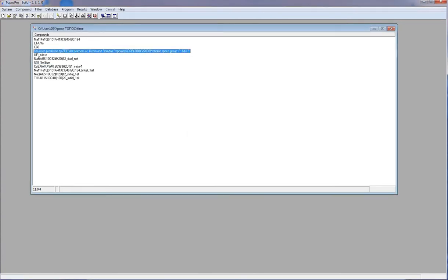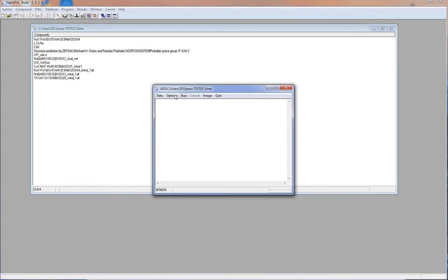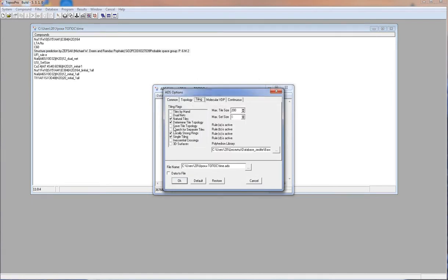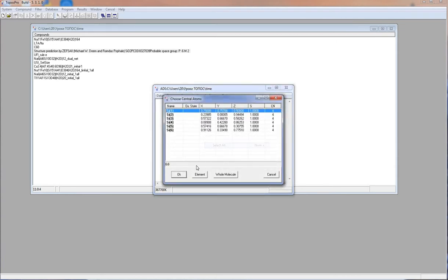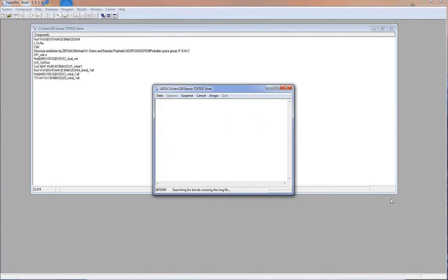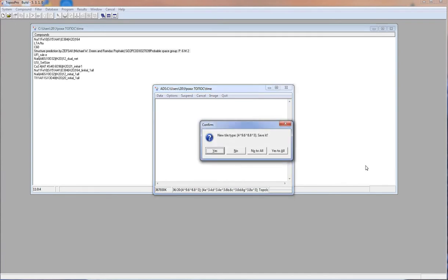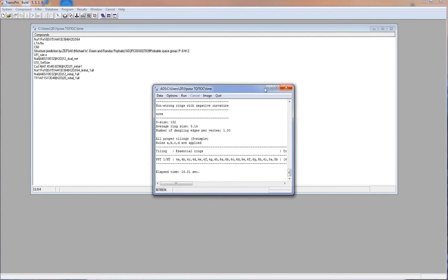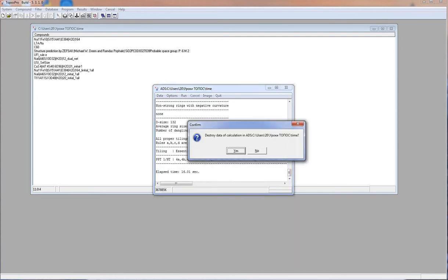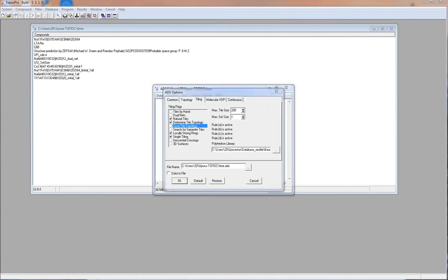The option Save Tile Topology writes names of the new tiles in the TileLib library. As you can see, now Topos has found a new tile and offers to save it in the TileLib. In this case, you should choose the tile's name. This option allows you to create your own library of tiles.